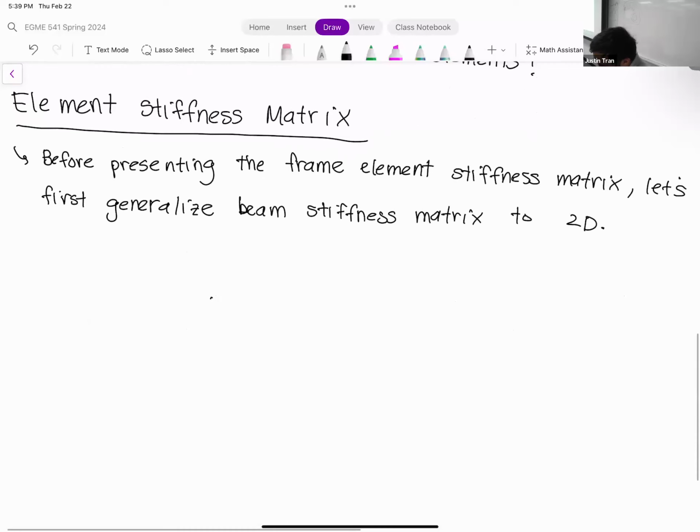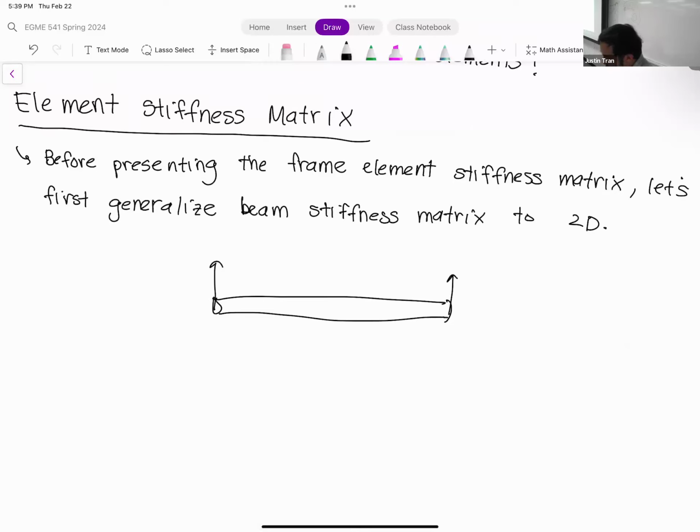You have your beam going one direction, and your deformation is perpendicular to this, so it already looks like a 2D situation. But if we have a beam element that's angled up with the horizontal like that, our deformation needs to accommodate for that as well. So we can apply the same kind of transformation matrix that we did before to this system.